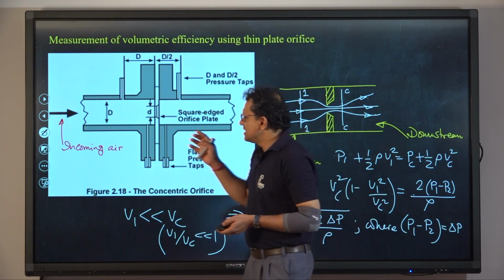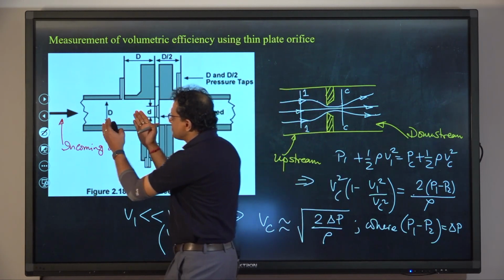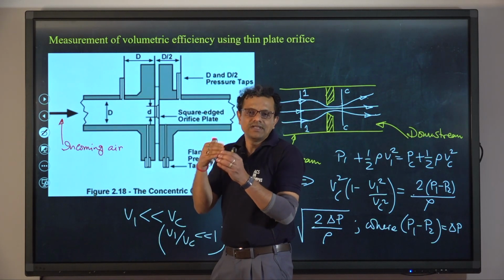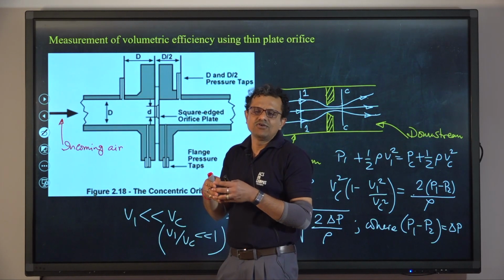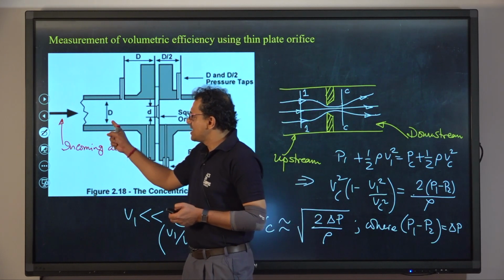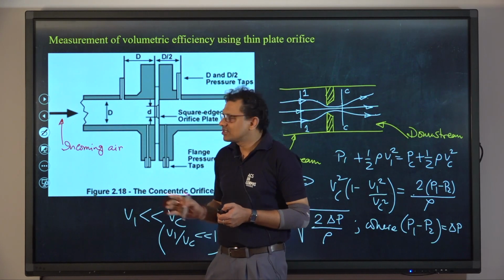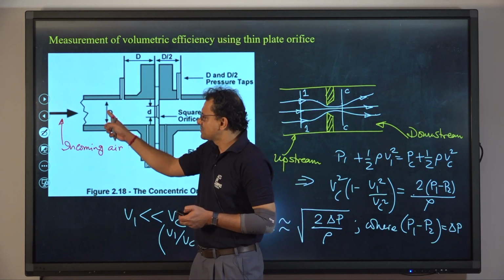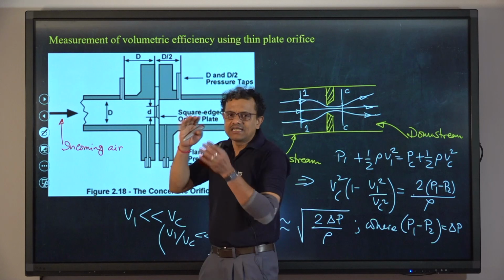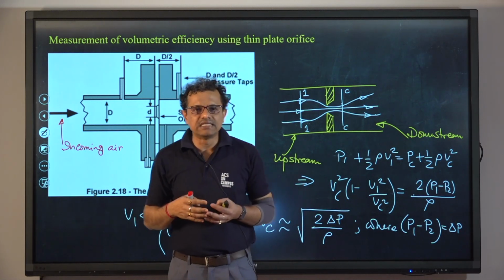Now the question is, the size of the tank should be very large so that unsteadiness can be minimized. It cannot be made zero, but it can be minimized. So typically a large tank is attached to this device on the upstream side, and the size of the tank should be at least 50 times the displacement volume of the engine.